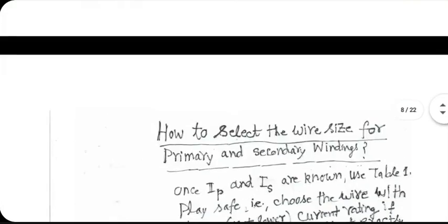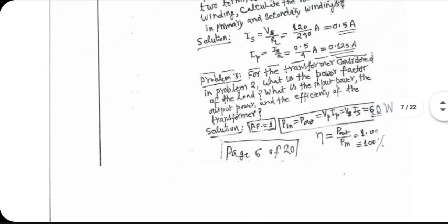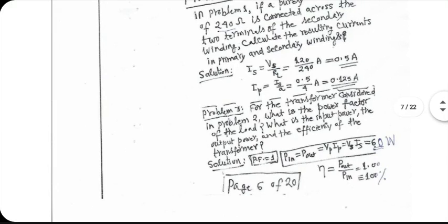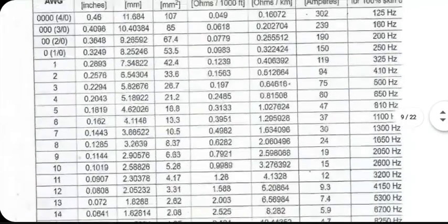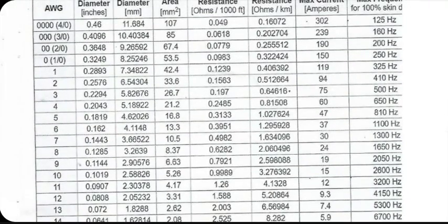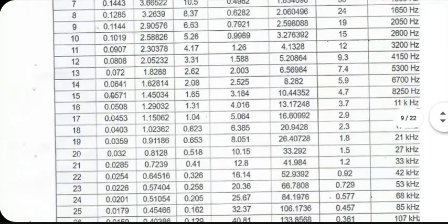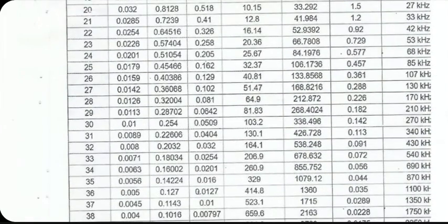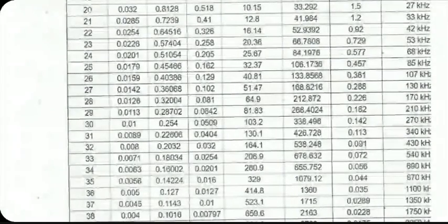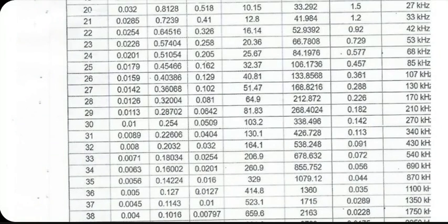So you need to remember the current, and current values are all RMS values in the table also. So primary winding, let's say full load current is known to us, 0.125 amperes. So try to read 0.125 ampere in the table or close enough. The closest is 0.142. You want to be safer, so go for the next. Don't choose 0.113.